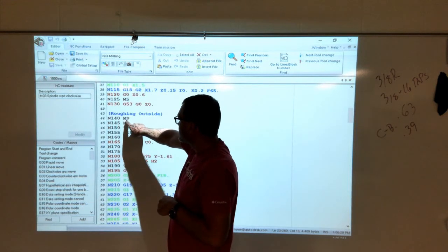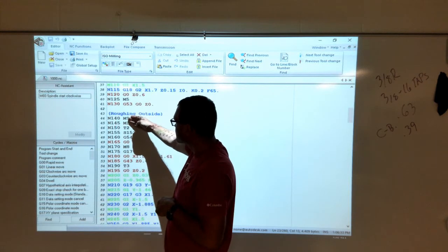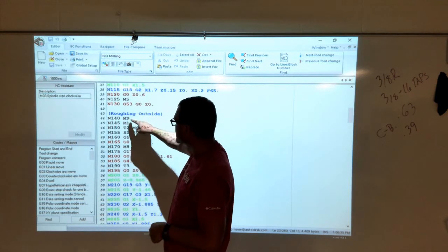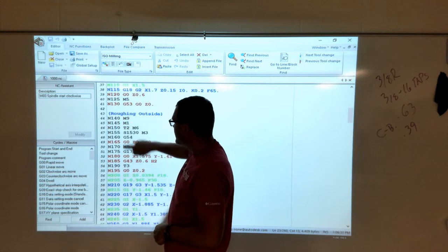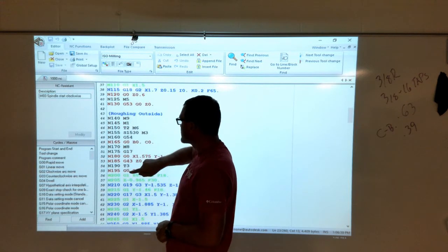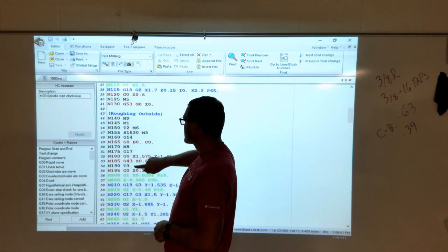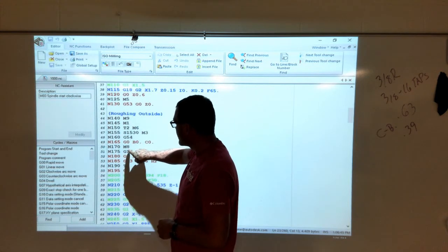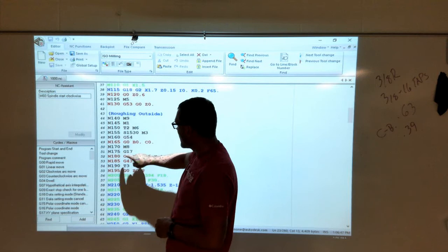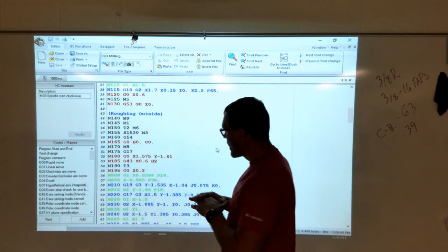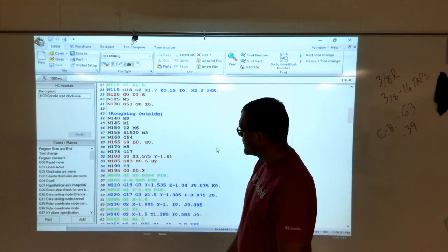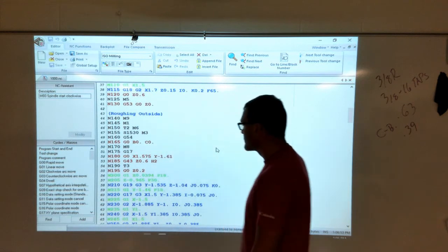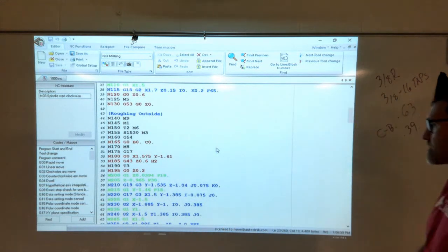But here you have our coolant off, which is really at the next set of commands. So coolant off, optional stop, then change tools, then turn our spindle on, G54, B and C indexing to 0, turn the coolant on, plane change, all of that stuff is coming through. Again, H2, so those things are all right. They're just going to be annoying.